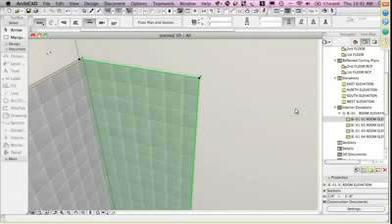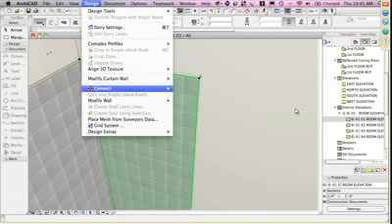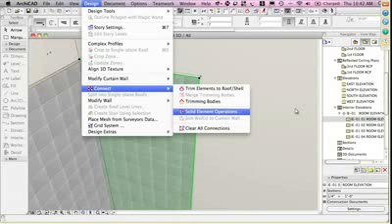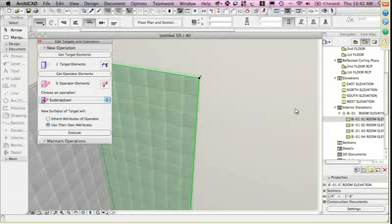So what we'd want to do is use the Design menu and get the Solid Element Operations, which are found in ArchiCAD 15 under the submenu called Connect. But if you're in ArchiCAD 10 through 14, you'd find it directly under the Design menu, Solid Element Operations. And I basically then say, this little piece of wall is the operator.